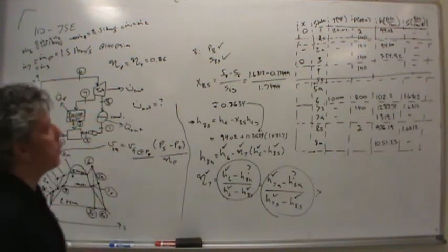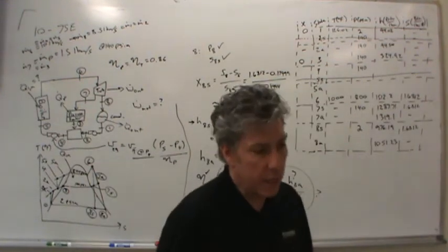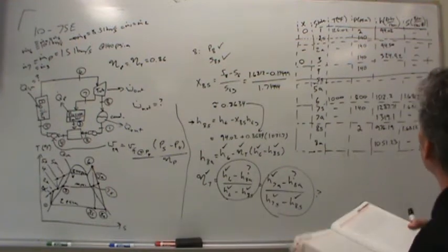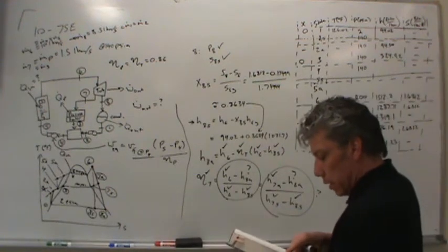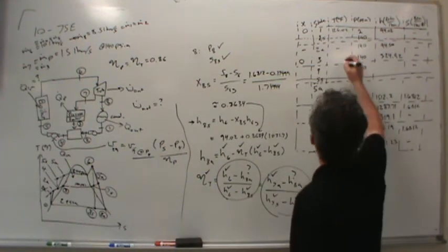Oh, there's a few states we still have to find, and I was curious what the temperature is at state 3, and that's something easy to figure out. All I really have to do is realize that state 3 is a saturated state at 140 psia. Look up 140 psia and write down the temperature. So that's 353.03 degrees Fahrenheit.